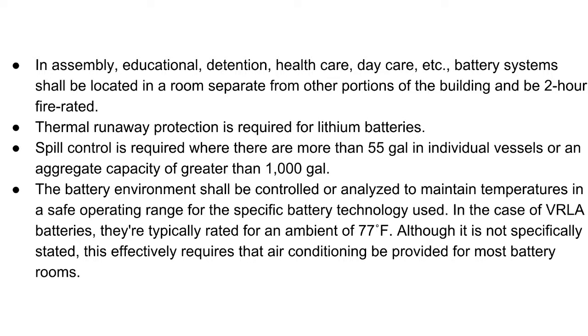So, if you're keeping your batteries in a garage and there's no plumbing and you're going to have to be watering these batteries, you can design an air conditioner system to come on during the day, ventilate the room, air condition the room when the batteries are at a full state of charge, and also create the water that you need to water the batteries. Get some synergy going.